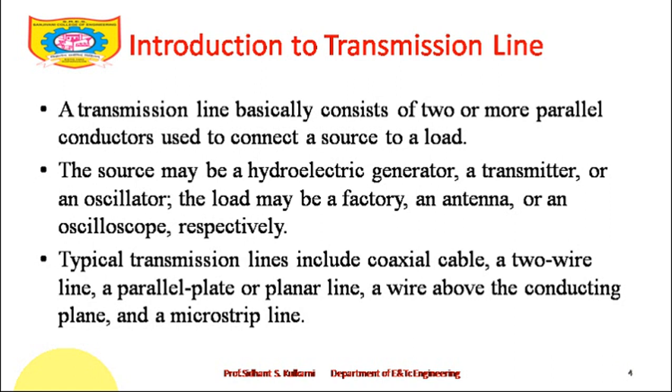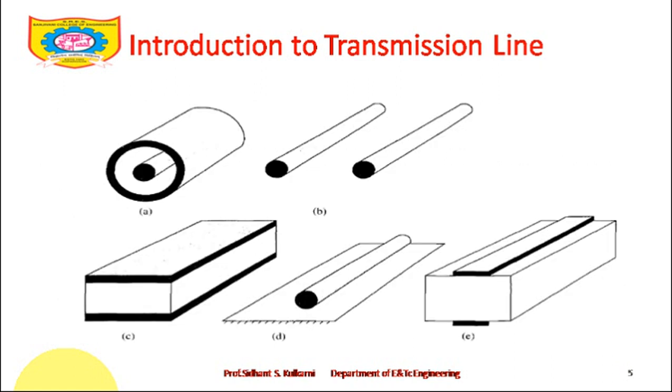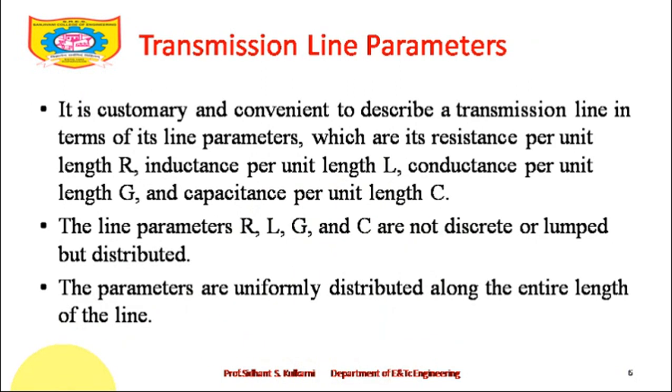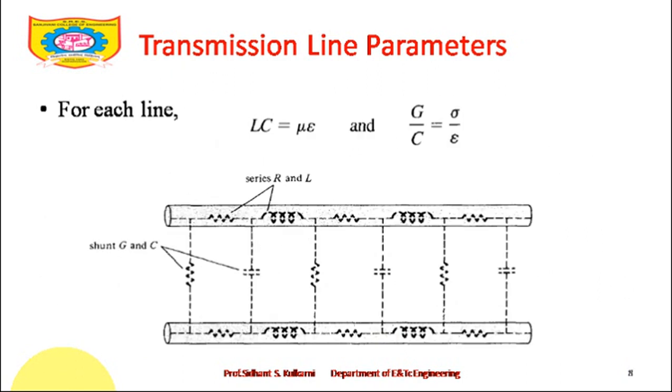There is one more type of guided media which we usually use, a waveguide, which is beyond the scope of this particular course. Then we went through the different structures like coaxial cable, parallel wire cable, microstrip line, conductor over a conducting sheet, etc. Then we started with the transmission line parameters, and looking at this diagram we came